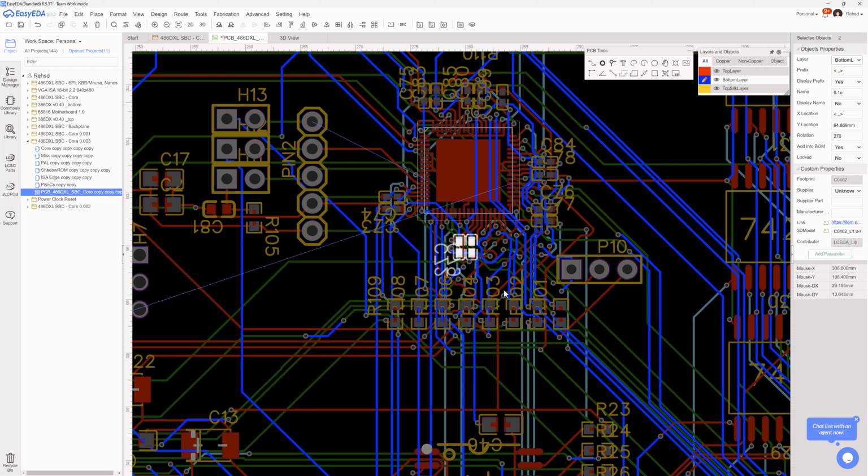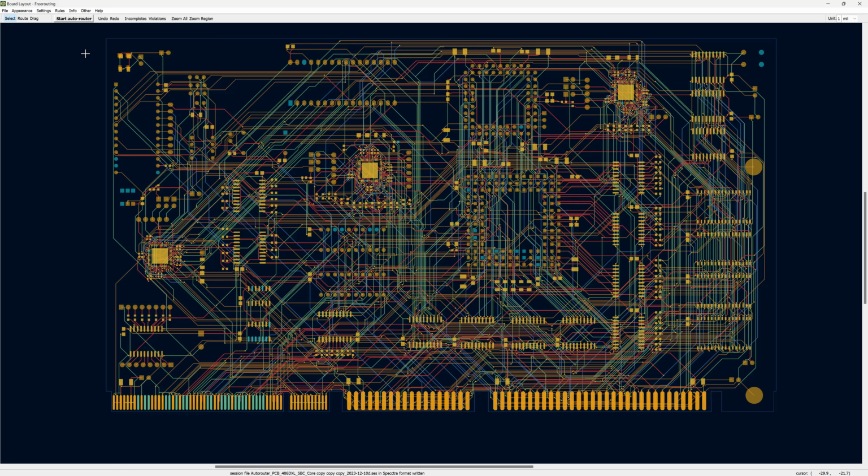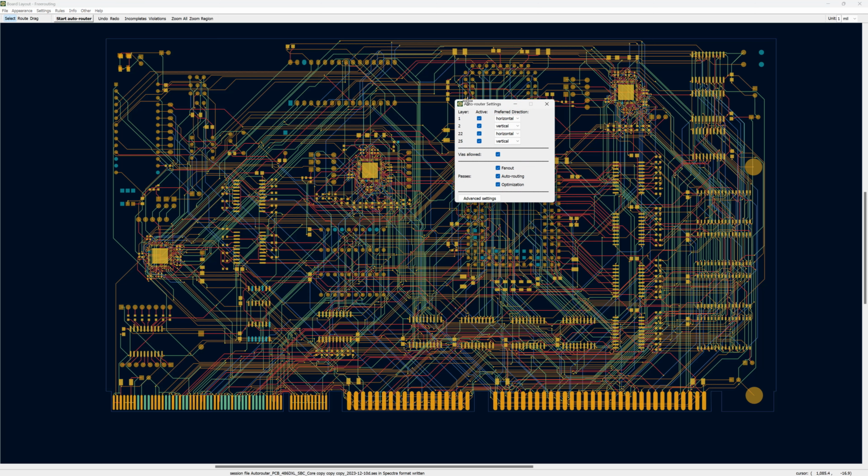Now, if I'm doing everything manually, then some of this is maybe less of a pain, but still I find that EasyEDA does not work well if you have inner planes. And I think it might be particularly inner ground planes, but I get rid of both the ground and the VCC. While I'm waiting for this, since it's still thinking hard, I'll look at the auto router I've been using, this free routing. It does have routing options, and I've just been experimenting with these for the fun of it.